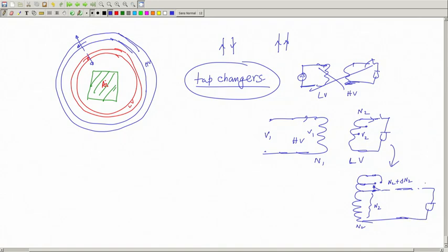You cannot do anything with the supply voltage here. Therefore, you simply increase a few turns. Voltage per turn is decided by V1 by N1, and if you increase 1-2 turns, you get more voltage. So, the regulation problem can be addressed a bit by this method.